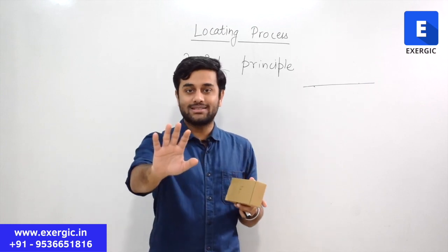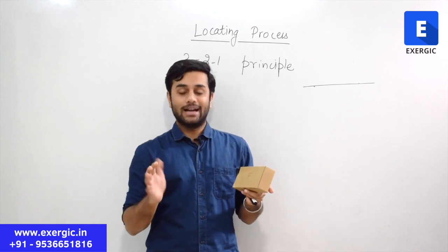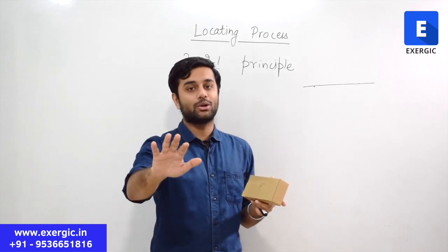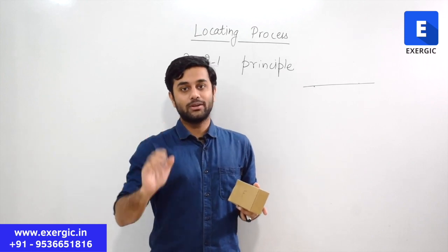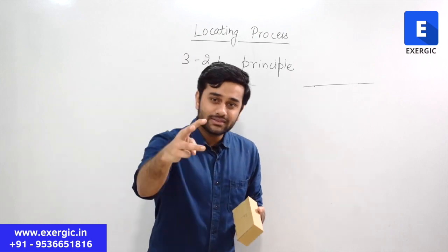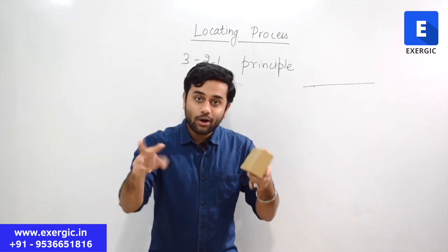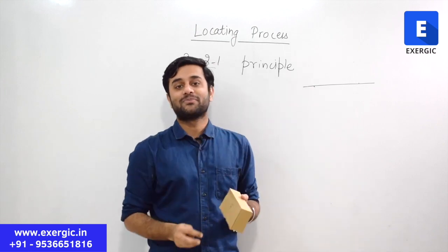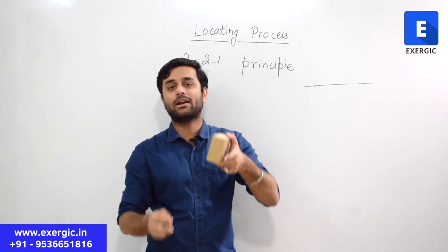If you are able to imagine, just pause the video, close your eyes and imagine what I am telling you. I am further explaining it. If you are not able to imagine, don't worry. But if you are able to imagine, you will enjoy this concept. 3 points are there. Even if the 3 points are not in the vertical plane, still all of them will be in touch with the workpiece, because the workpiece can align accordingly. There is a slight alignment required.